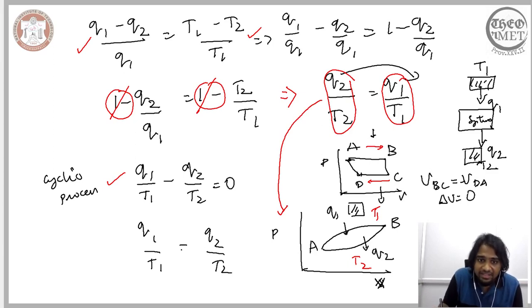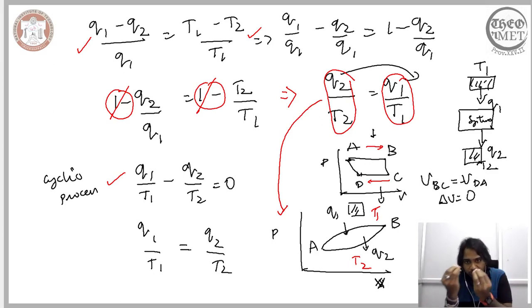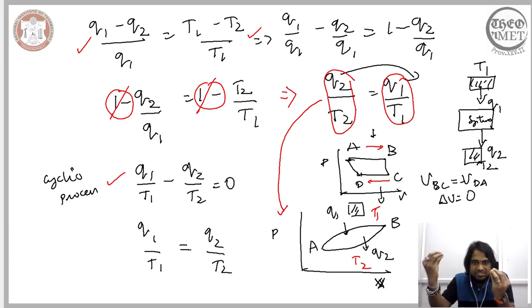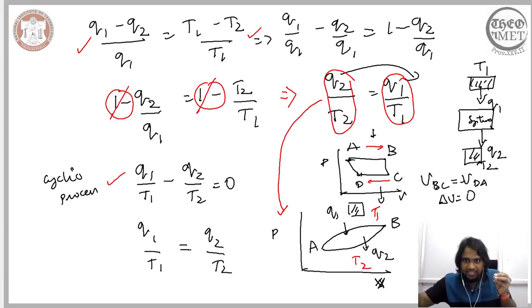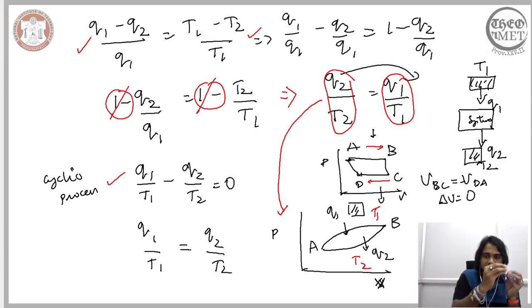Now since these are equal, the change in the system, the state of the system, gets reversed. Whenever there is a heat input Q1, there is a change in the state of the system. Whenever there is a loss of heat Q2, this change is reversed back to A. So we have a cyclic process, and this cyclic process is also reversible because we started at a state, went to a different state, and from that state, when we lose a specific amount of heat, we got back to the original state.